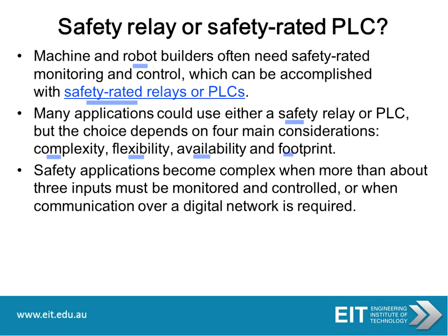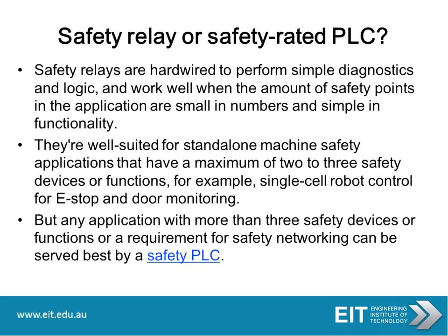So your safety applications become complex when more than about 3 inputs must be monitored. So that's the guideline: more than 3 inputs to be monitored and controlled, or when communication over a digital network is required. So that's where your safety applications become complex.